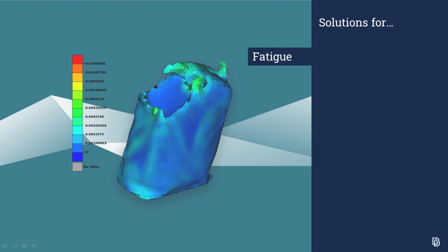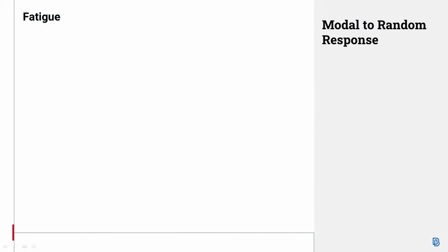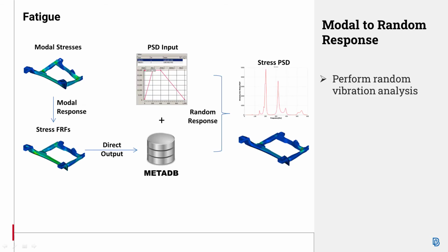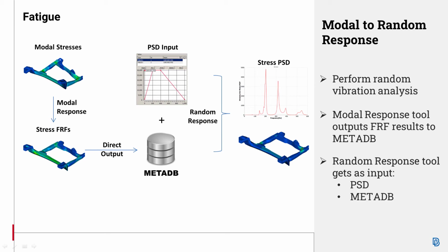Regarding solutions for fatigue, through the new features of modal response and random response tool, it is now possible to perform a random vibration analysis given the modal stresses of the structure and the PSD of the excitation. In specific, the modal response tool is now able to output results into MetaDB format directly. Random response tool supports the MetaDB format as frequency response input, and together with the PSD, the random vibration analysis is performed.